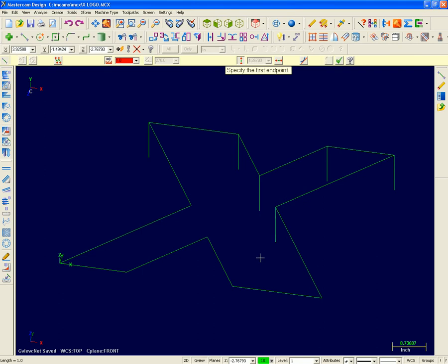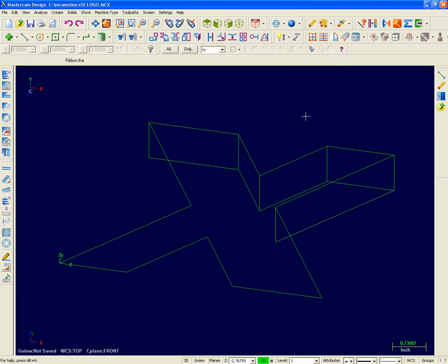Alright, I'll turn my 3D mode on and create the profile now using the multi-line creation. This icon enables multi-line mode. I will unlock my line length and turn off vertical mode. So I'll just go ahead and create these lines. Notice I didn't have to change my plane or Z depth while in 3D mode.